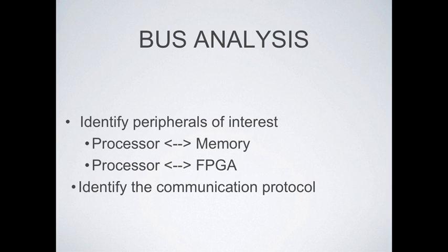So moving on to bus analysis. What you need to do when you first start bus analysis is identify the peripherals of interest. So what are you trying to go after? What are you looking at? You're more than likely going to be performing bus analysis with components that are attached to the processor, because the processor is the one that talks to all of its peripherals.